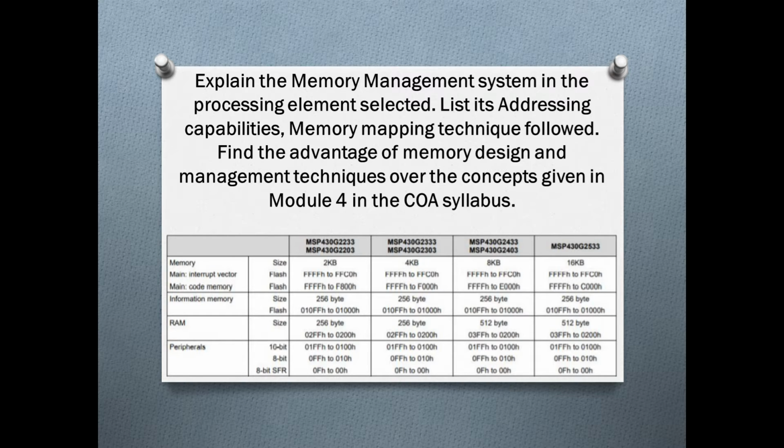The peripheral modules are located in two different address spaces. The special function registers are byte oriented by hardware. The peripheral modules that are byte oriented by hardware are mapped into the address space from 010H to 0FFH, and peripheral modules that are word oriented by hardware are mapped into the address space from 100H up to 01FFH.